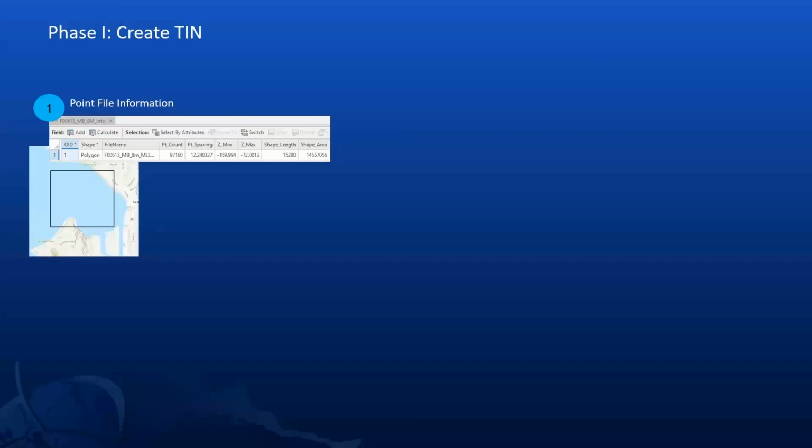So these first couple of tools that you use are if your input is point data like XYZ. And I'm starting with XYZ just because that does require the most tools. So it's, I guess, the most complex workflow. But you could also use BAGs, or you could use raster like GeoTIFF if you want to. Just so long as you have some 3D data, you can use it to generate these features. And I'll talk about where you would start in the workflow if you are starting with a GeoTIFF or a BAG or something like that, something other than, say, an XYZ data set.